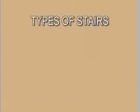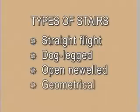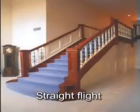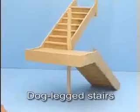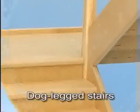The terms used to classify stairs are derived from their methods of construction. The straight flight does not change direction throughout its length. Dog-legged stairs have the string of the upper flight directly above the string of the lower flight and share a common newel post.